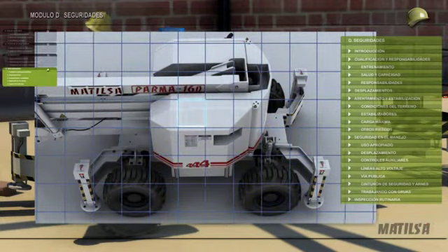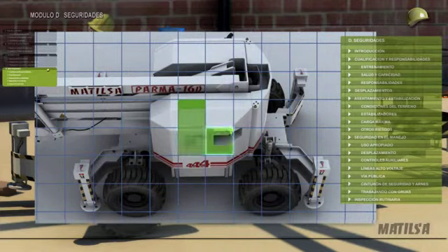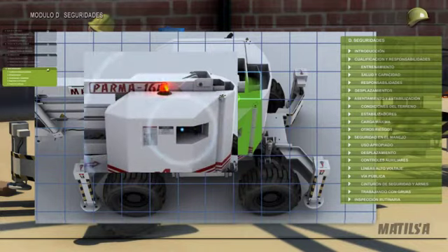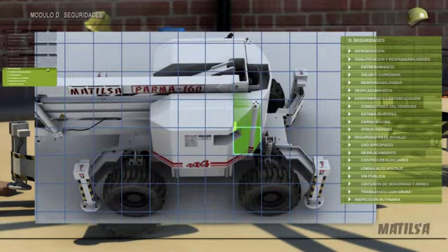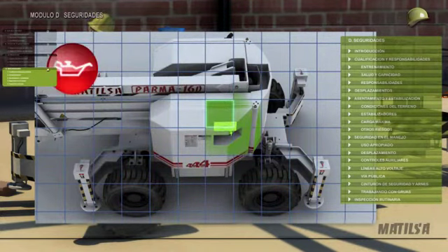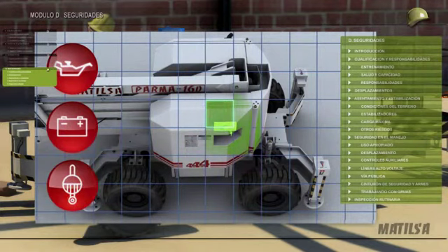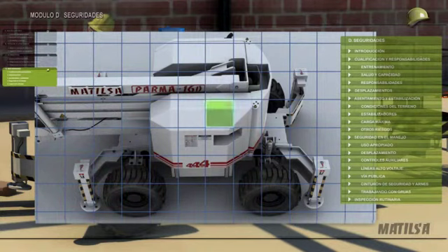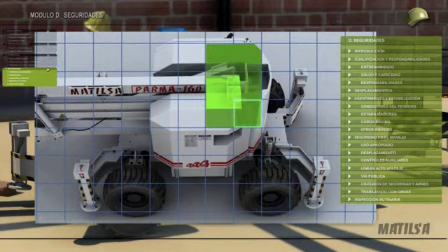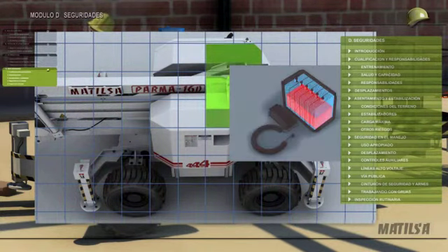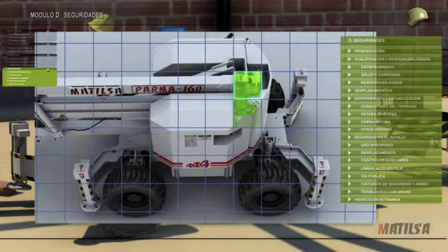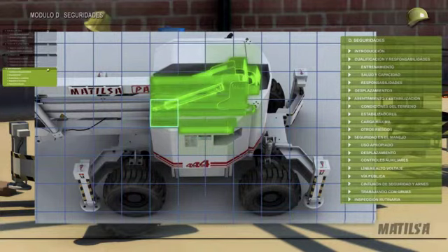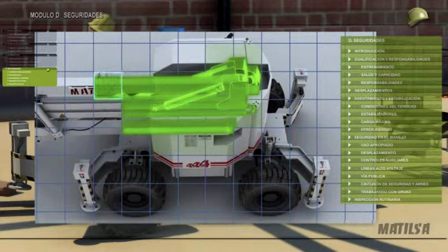The acoustic lights, signals and safety devices must be in good condition. The levels of oil, water, batteries, hydraulic oil and diesel oil will have to be checked. The batteries will have to be free of all corrosion and with a suitable distilled water level before each load. Avoid dripping hydraulic oil. This contaminates the surroundings and soils the ground.